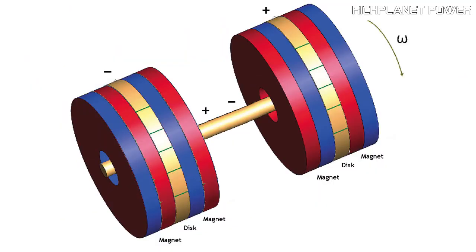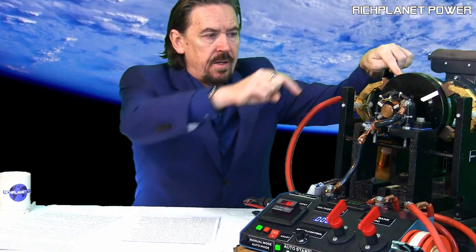So the two generators can just be connected in series by fitting them on the same shaft, just like connecting two batteries in series. And the shaft, which is the positive of one and the negative of the other, connects the two together, resulting in twice the output voltage. This means that there is now no terminal on the shaft, and the voltage terminals are on the rim of the two discs. So there'll be two of these discs, and one is positive and one is negative. Therefore, two identical liquid brush arrangements could be made around the rims of each disc.